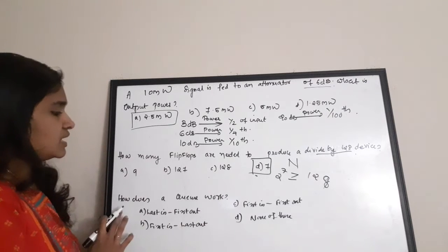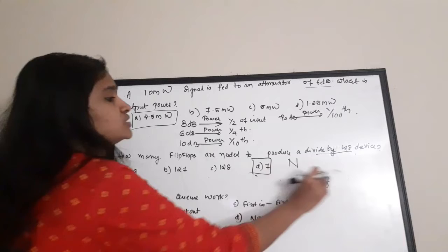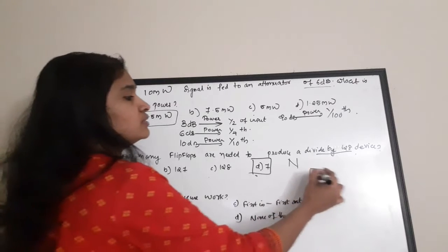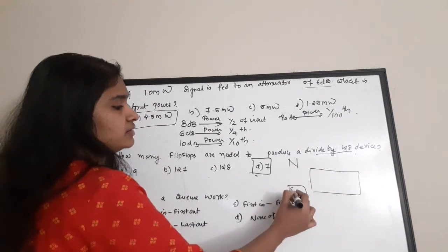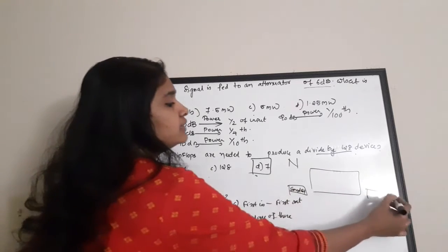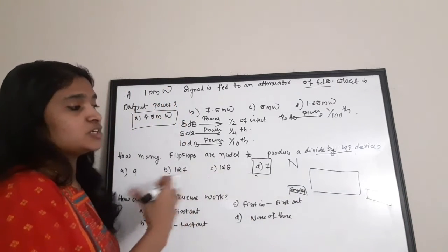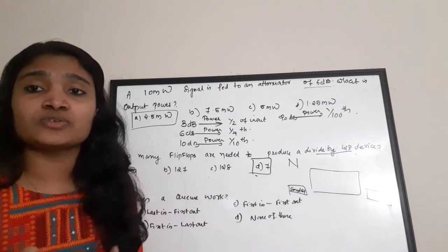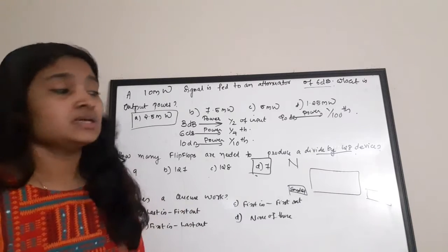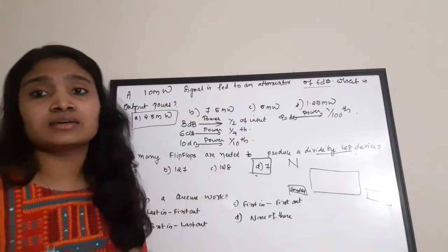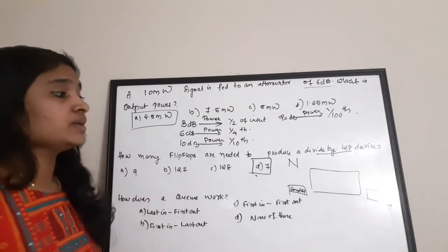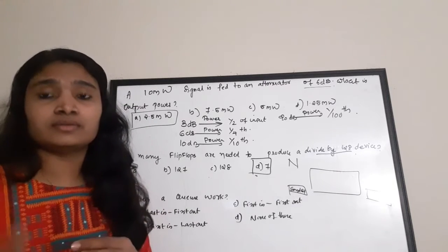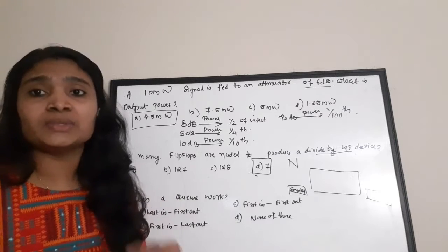Okay. Next question. How does a queue work? Here we are going to talk about message queues, or simply queues. Say this is a message queue. There will be a sender. These are inter-process communication mechanisms. Message queues are used for sending and receiving messages. So they are inter-process or inter-task synchronization and communication mechanisms. That is, they are used for communicating between two tasks. One task uses a message queue to communicate with another task.